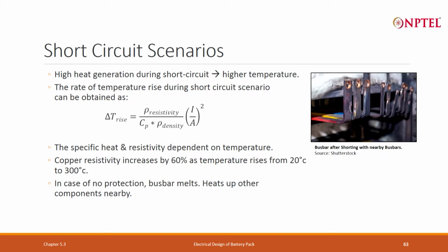Now, your whole battery pack is not usable. So, what do we do in such a situation? We have some protection circuit. As soon as it detects the current surge, it will try to disconnect the current path.